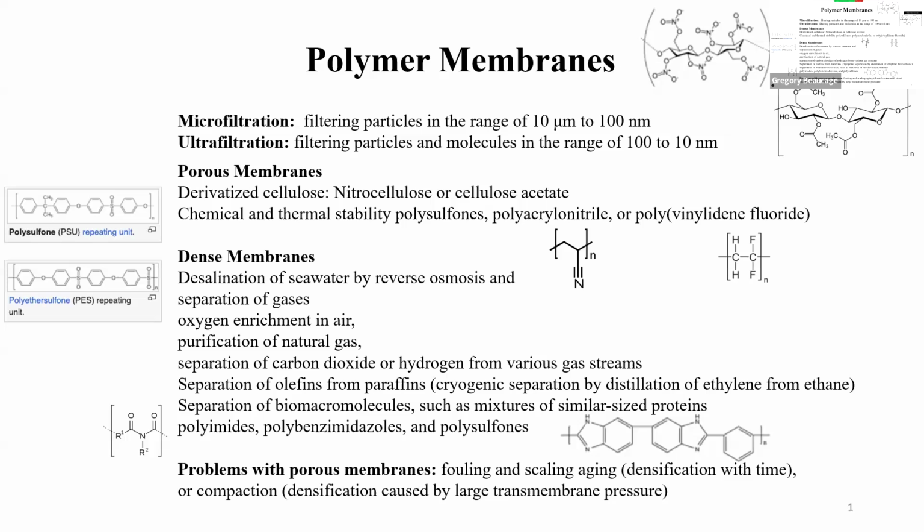Another way is you could take polypropylene film that's semi-crystalline and stretch it, and it rips holes into the material. And if you do it in the right way, then you get pores like that. So for this kind of large scale porous films, there's a variety of ways to get it. Right. Then as you get smaller, it gets harder, right? As you try to make nanopores, you're going to have to use some techniques that are different than that. Right.